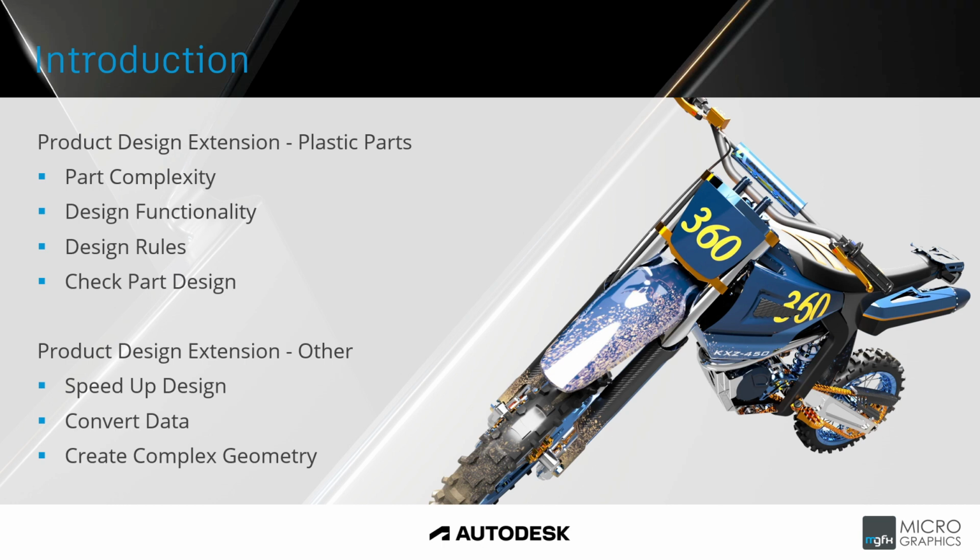At the end of the design process, we would be able to run checks for specific issues related to the part itself and the manufacturability of it. Let's say we're looking at injection molding. We can look at the part and answer questions such as, are there areas that are too thick? Are there areas that have knife edges? Are there areas that don't adhere to those design rules that were specified? There are tools in the product design extension that will help with plastic part design.